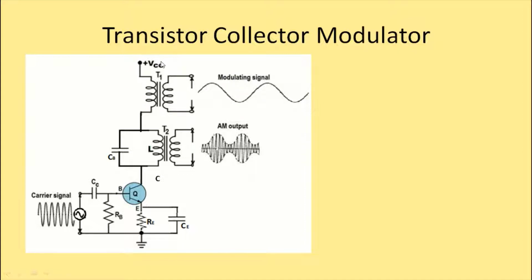And this is the secondary of the transformer. To the secondary, if you observe this side, we have connected VCC. This is nothing but the DC voltage which we are using to bias the particular transistor here. Biasing is nothing but giving some suitable voltage to the transistor so that the transistor is ready for operation. We will deal with biasing in detail in the later chapters.